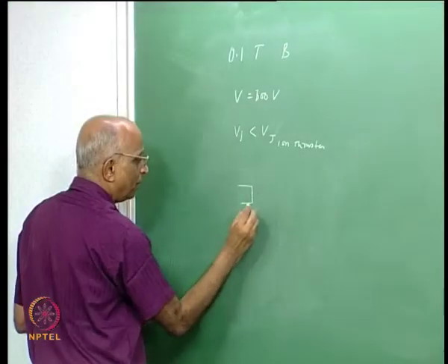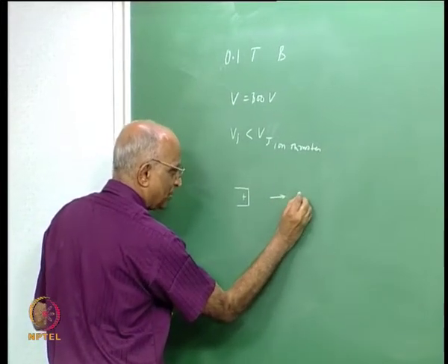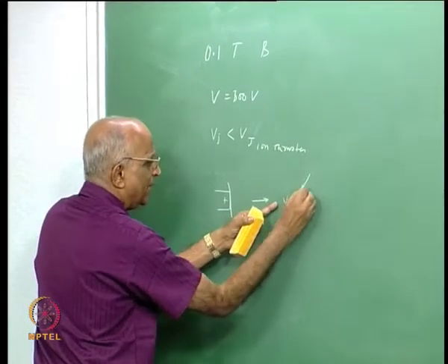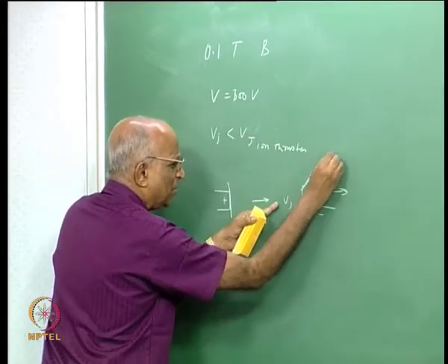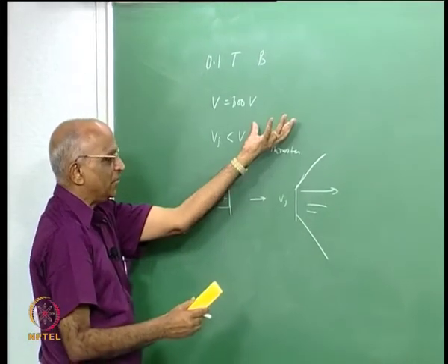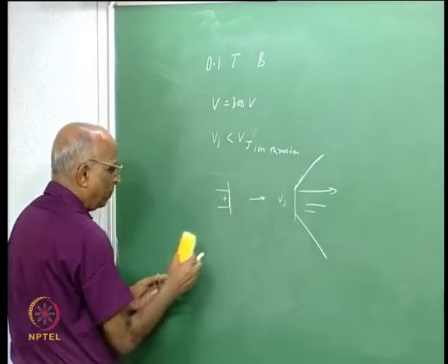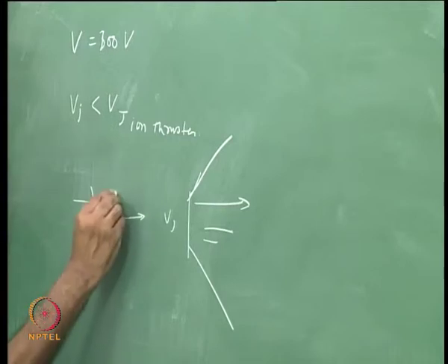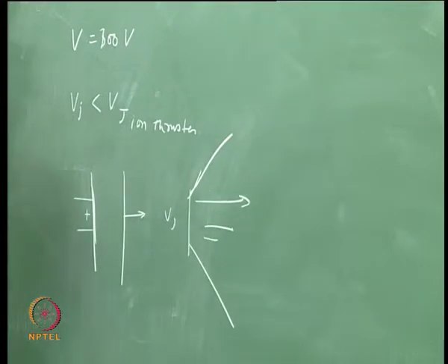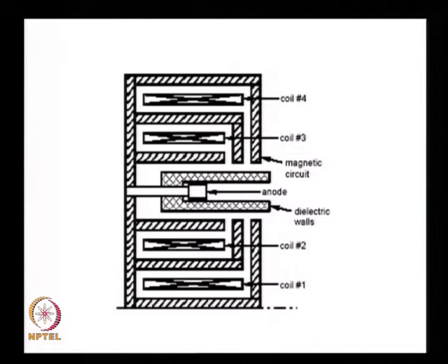You have the anode, you are positive, it is pushing out the charges with some velocity, and therefore the velocity being lower, it does not really go as a free stream, it tends to diverge a little bit, and when it diverges, it goes and contaminates the other bodies, spacecraft around it. To be able to prevent it, people talk in terms of something, can I reduce the length over here such that the positive charge is more effective, and that is what I also show here after a couple of slides. Let us take a look at it.